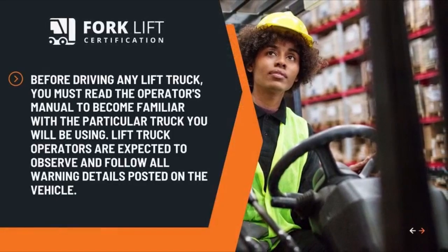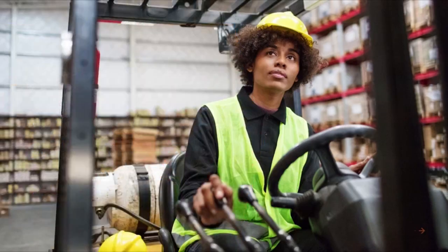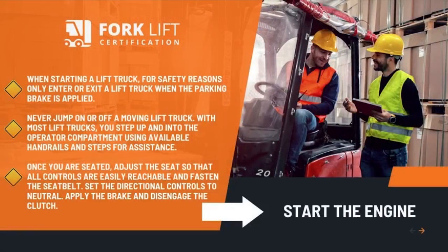Before driving any lift truck, you must read the operator's manual to become familiar with the particular truck you will be using. Lift truck operators are expected to observe and follow all warning details posted on the vehicle. When starting a lift truck, for safety reasons, only enter or exit a lift truck when the parking brake is applied. Never jump on or off a moving lift truck.